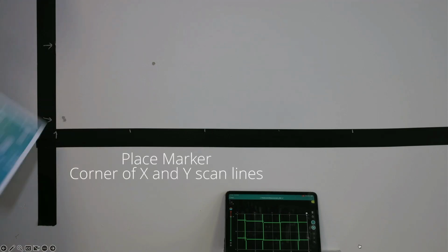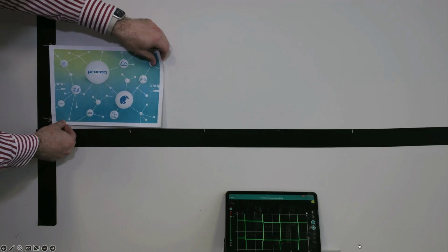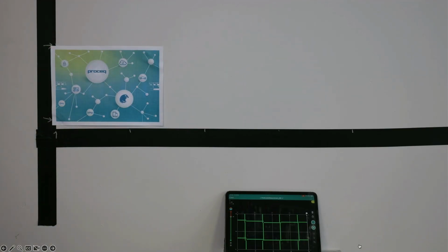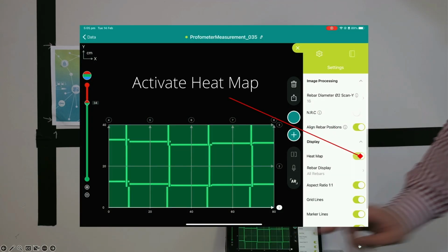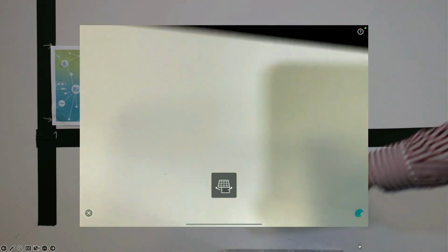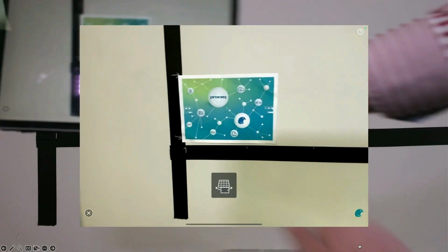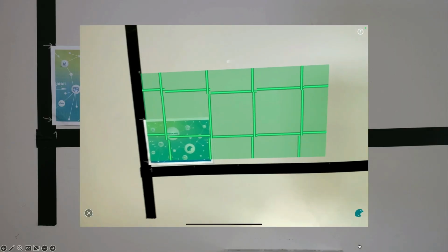now if you do use the area scan functionality, because it is a Screening Eagle or ProSec radar, we also have the augmented reality presentation. So with a marker at the origin, I can project the position and heat map of those bars onto my structure. And that's sort of a full demo of the PM8000's current general operation. I do have a more detailed webinar about PM8000 operation in particular I've done previously, but there's just to give you a good overview of what's achievable.